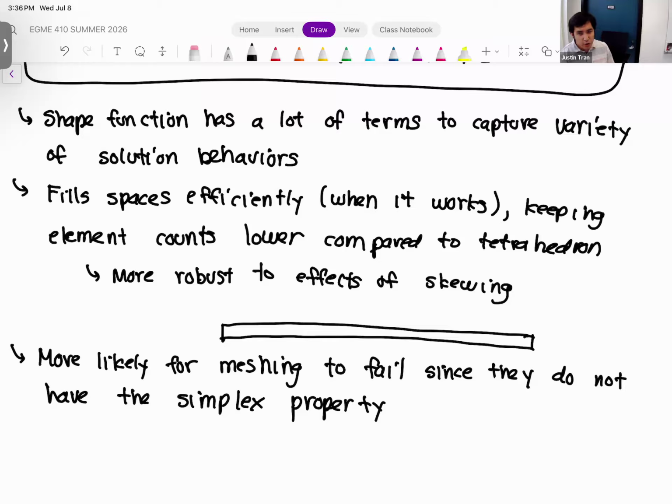Yeah, you start to get a feel for it too, once you mesh quite a bit. For a lot of the work that I do, I run simulations on biological geometries, working with CAD files of people's blood vessels, which are very strange, not standard geometries at all. So I knew that even if I had a hexahedron mesh available to me, it would be very difficult to get a mesh in those situations, because the geometries are so unique and strange. So I just go for tetrahedron right away, and I rely on mesh refinement to get the accuracy that I need.